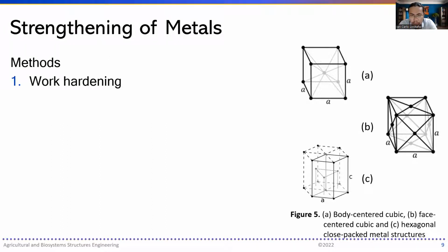Metals have the metallic structure. So with work hardening, there is dislocation and generation of structures, so they are forced together. That strengthens the metal. This is good for metals such as iron, since iron is a metal with a high melting point and is non-brittle. One example of work hardening as it happens in fabrication is via machining. When you machine metals, there is work hardening.